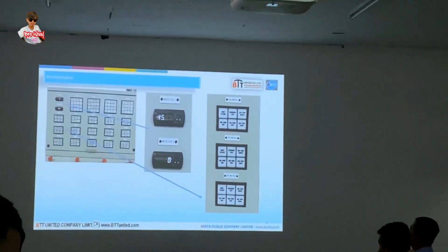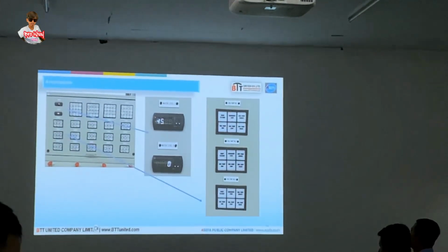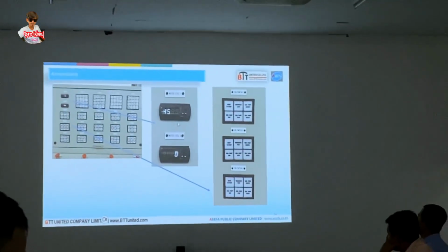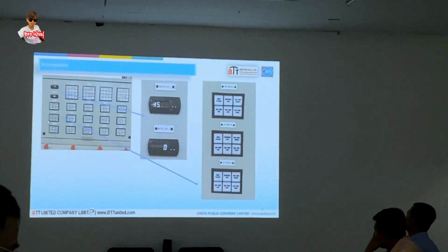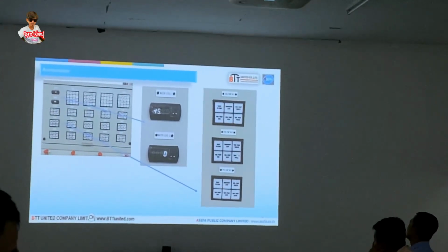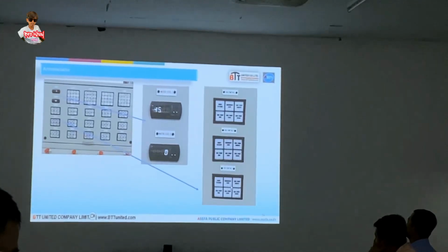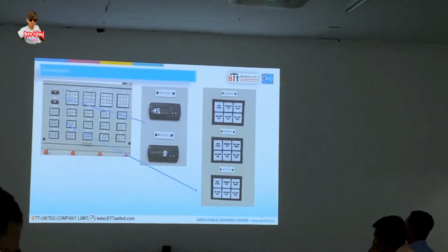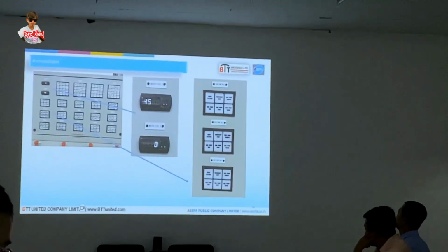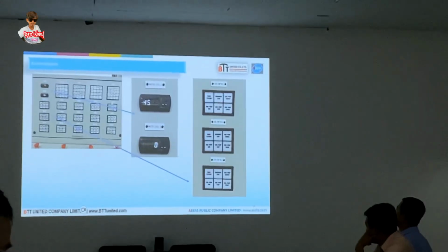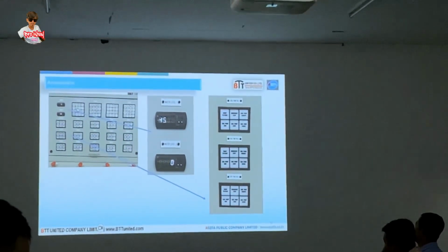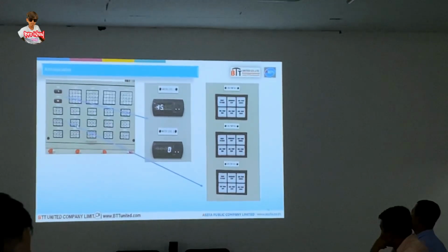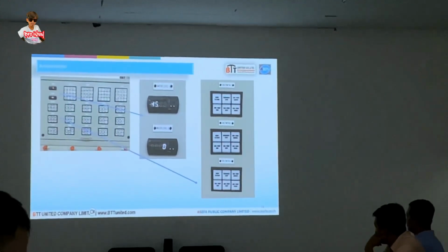Looking closer, on the left side you have 2 displays for the water level. Number 1, number 2: we have 2 sensors to monitor the water level at each side, at each pump. And right underneath them, there are submersible number 1, submersible number 2, and submersible number 3. On the right side, if you go vertically, this is pump number 1, pump number 2, pump number 3, and pump number 4. The top part will have all the alarms for the main pump, and you'll have the oil pump, the air fan, and all the accessory alarms.